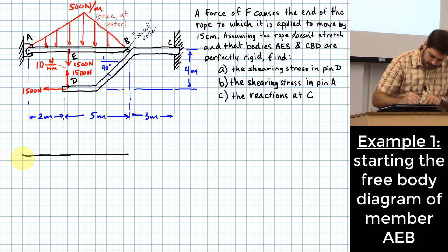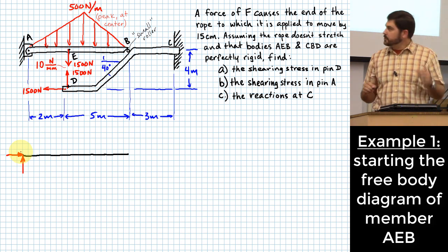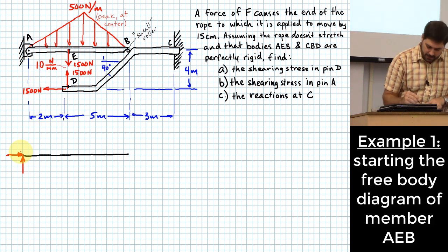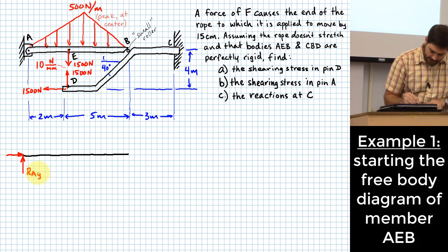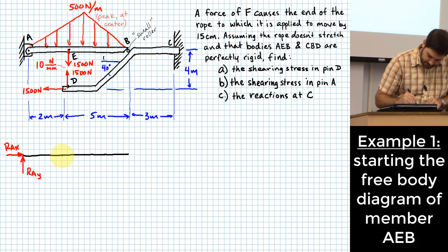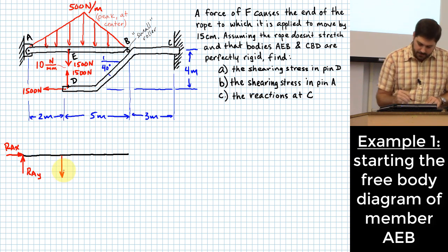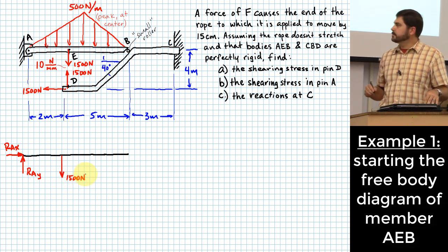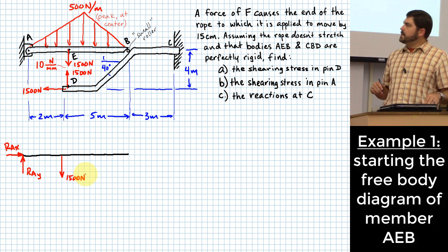Okay. So the easy one to look at quickly is the reaction forces at A. We know this because it's a pin, and a pinned connection connected to a rigid support like that has two components of reaction possible that hold it where it needs to be. So I'll call this RAY and this RAX. Okay, another one that's relatively easy is what? E. 1,500 newtons. Okay, so those are the easy ones.